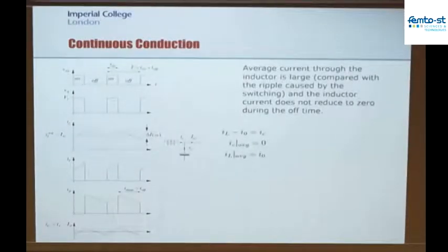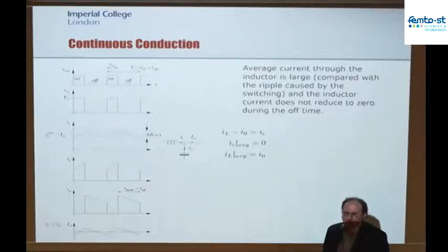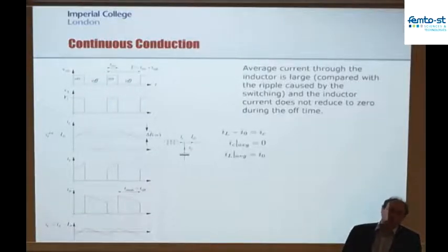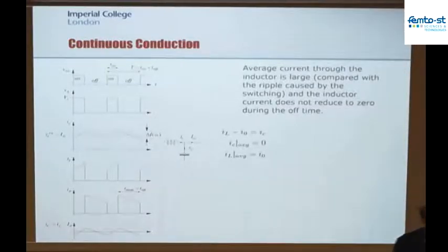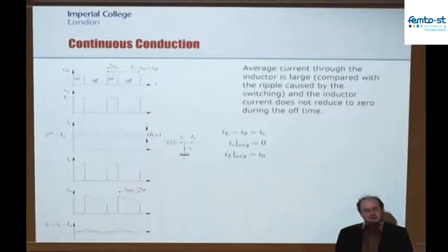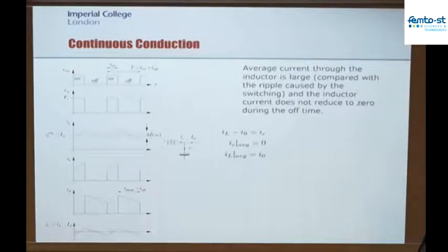When you look at other circuit topologies, there's a common circuit topology called an isolated flyback converter, which uses a transformer core as the energy storage mechanism. It's very common for people to design those in discontinuous mode to minimize the size of the core and to minimize the cost. So that type of power supply is used very often in pieces of consumer electronics like DVD players, Sky set-top boxes, that sort of thing. They will typically have a flyback converter, typically operating in discontinuous mode, because cost is such a huge driver in making the power electronics for those things that if they can shave 20% off the volume of the core, they can save 20% of the cost of the core.